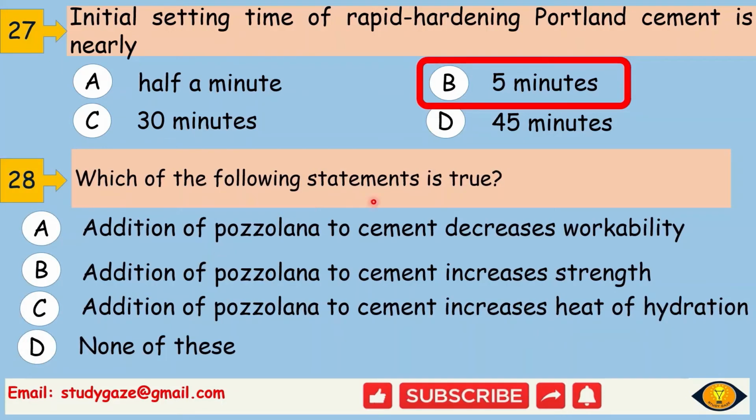Which of the following statements is true? So the true statement is none of these, because addition of pozzolana to cement decreases workability. It is also an incorrect statement that addition of pozzolana to cement increases strength. It is also an incorrect statement that addition of pozzolana to cement increases heat of hydration. So none of these is the true statement. Okay. Next,